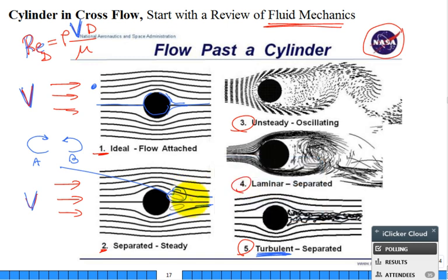To answer that question, I would focus on this region right in there, where you have the fluid line on the top definitely going from left to right, and the fluid that's right below it, in that recirculating region, really can't be doing the opposite. It makes more sense that it's being dragged in the same direction. So it makes more sense that A is correct, because on the top outside it's going from left to right. So the correct answer is A.